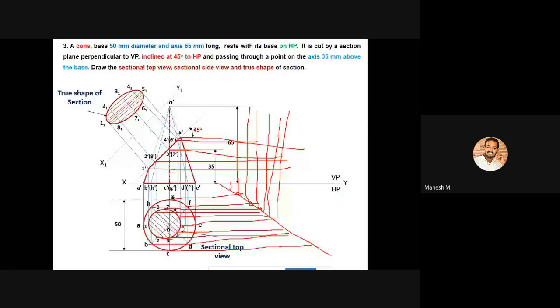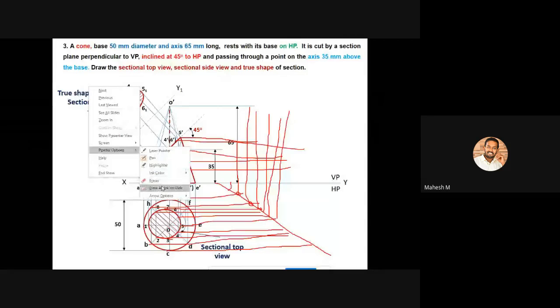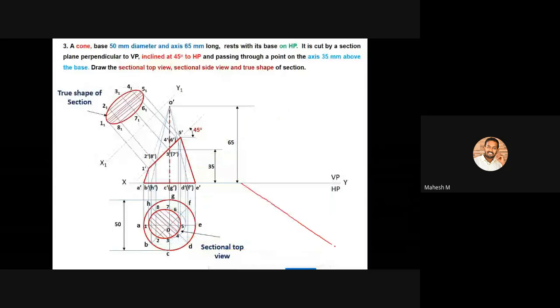Okay, so you have to project all the points. After doing that, you'll be having an intersection for each and every notation. That means point number 1, for example: I'm going to show the 45-degree inclined line that is created. I'm going to project this particular point number 1 towards this inclined line.